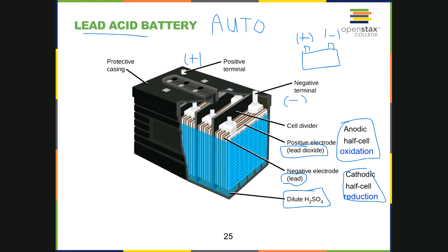because when you rapidly recharge a battery, you're going to produce some hydrogen gas. And hydrogen gas is flammable, it's explosive if you have the right combination of hydrogen gas to the oxygen in the surrounding air. So now you've got an exploding device that has sulfuric acid in there. That's not a great combination, because of course if you get the sulfuric acid in your face, you're going to have burns, you might be blinded, some bad things have happened. So we want to be careful about this.